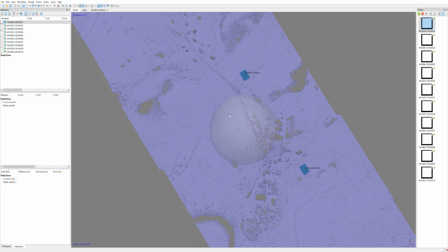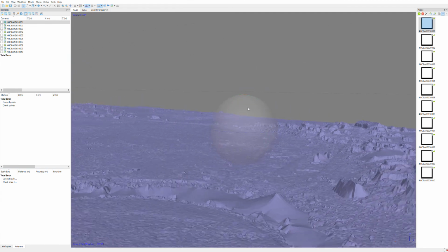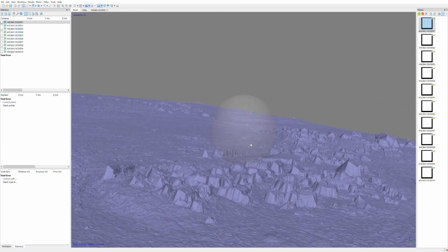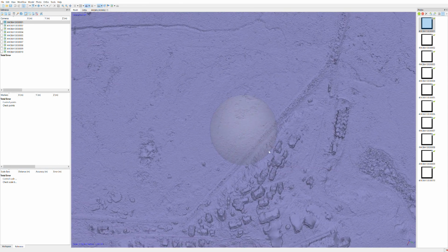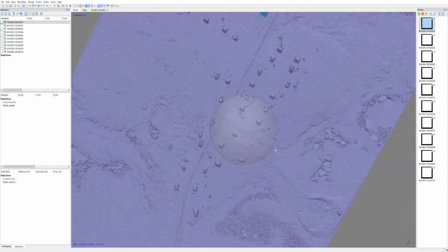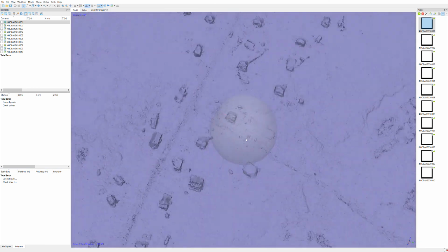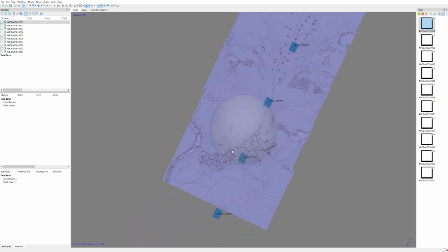You can look at advanced, and interpolation should be the default, so leave that there. You could do vertex colors, but we're not going to. So it connected all those points together, and you can see now there's some obvious noise in the rivers and around the buildings, which kind of look like strange tents, but overall it worked really well, and it was fast, it was easy, and it gives a really good idea of what the place looks like. This will help, because remember, orthorectifying, the whole point is things on hillsides and stuff.